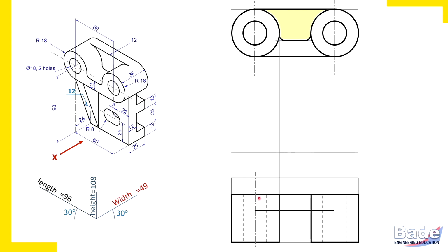So I have erased those two edges. And watch these small curves here. These small curves are a diagrammatical representation that indicates a tangential joint between two surfaces. So when a flat surface meets a curved surface tangentially, then in orthographic views, this is how we denote that tangential joint. And that sharp edge, which I erased here just now, is replaced by this curve, indicating it is not a sharp edge here, but a tangential joint. So this is how we have corrected the joints here.